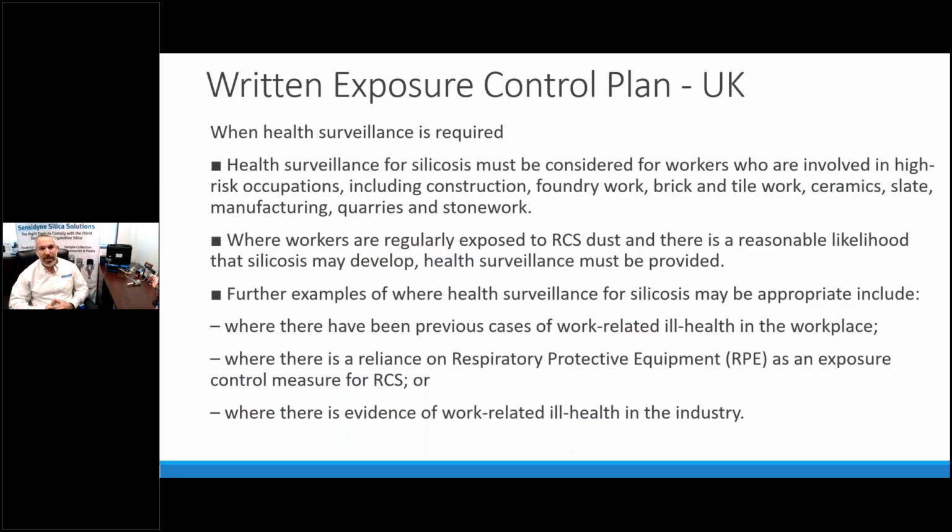So what do these written exposure control plans look like? Well, health surveillance for silicosis must be considered for workers in these high-risk occupations. This includes industries like construction, foundry work, brick and tile work, different quarry work and stone work, where workers are regularly exposed to respirable crystalline silica, and there is reasonable belief that silicosis may develop. Health surveillance must be provided.